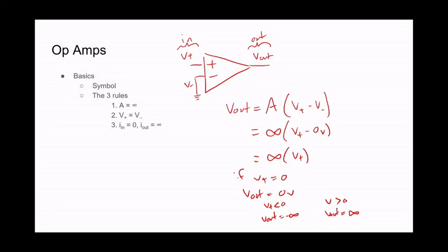The reason we can make these grand observations is because we're not mathematicians, we're engineers, so we make approximations like this. This explains our first rule. Usually you would call this a comparator, where you're comparing the input and, if there's any change, magnifying that to the maximum voltage possible. Obviously, it's not going to go to negative infinity volts. It will be limited to the negative power, and the same with positive: it would be whatever the positive power is.